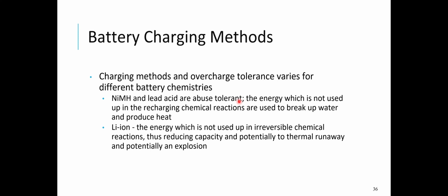On the other hand, lithium-ion batteries can be permanently damaged if you overcharge them, and if you do it very quickly, because irreversible chemical reactions occur if I keep charging a lithium-ion battery, so their capacity reduces. And more importantly, if I keep a lithium-ion battery charging, it'll eventually explode. It'll heat up and heat up and heat up and explode.